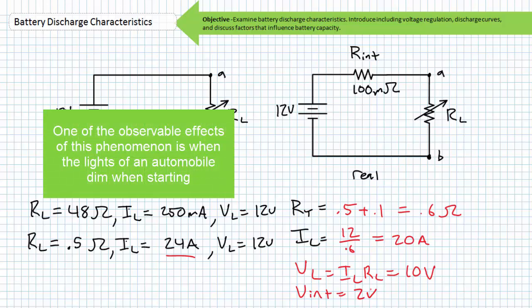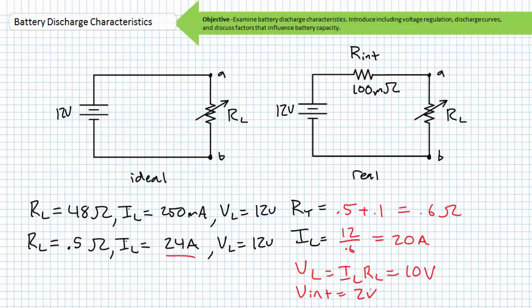This is to suggest that the working voltage observed at the accessible terminals of the battery will decrease during periods of excessive current draw. The greater the internal resistance and the greater the current draw, the more observable these effects become. Power is lost to the internal resistance of the battery and unavailable to the electrical load.